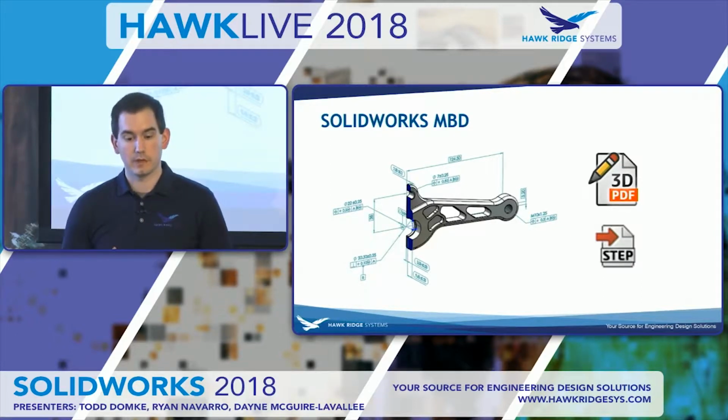And basically we're working towards a future where if you need to send a file to the machine shop or an outside vendor, you're only going to have to send that one STEP file because it's already going to have all the dimensions and everything else built onto it. So you won't have to do a drawing and a file anymore. So look out for that in the industry. STEP 242 is going to become more and more common.